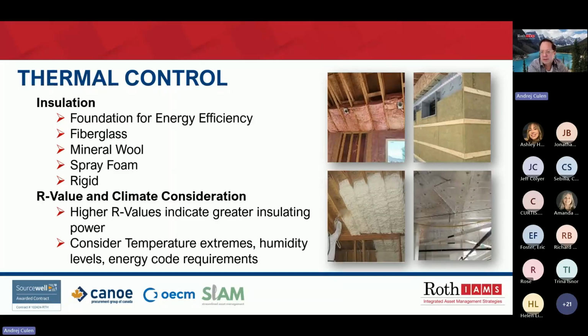The effectiveness of insulation is measured by its thermal resistance, or R value. Higher R values indicate greater insulating power. To select the appropriate insulation for specific climate and building requirements, consider local temperature extremes, humidity levels, and energy code requirements.